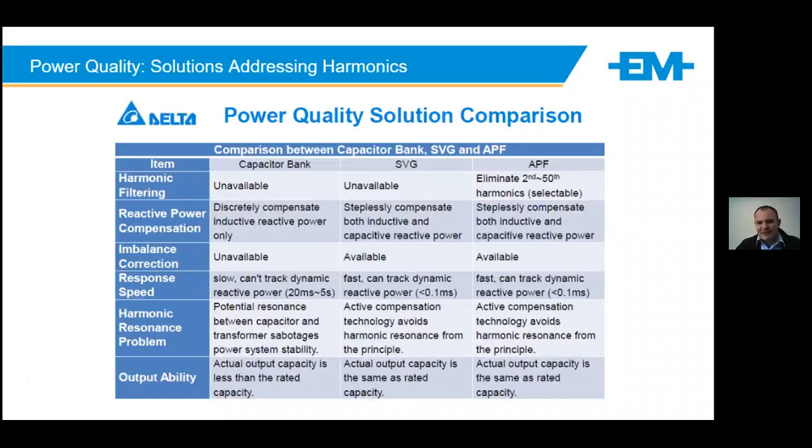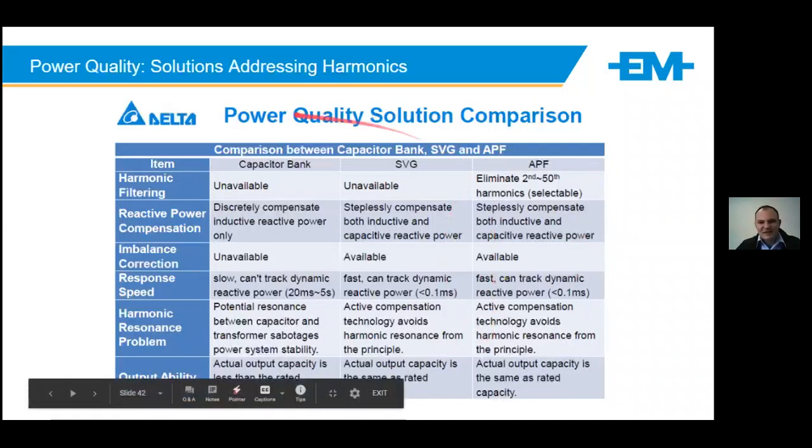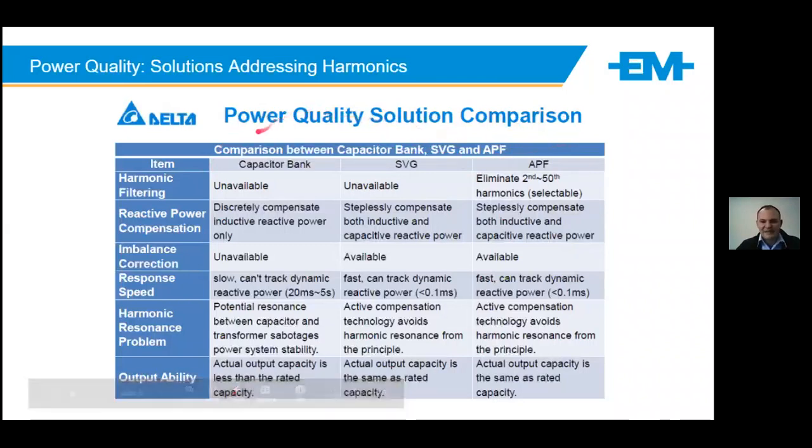An active power filter can do leading and lagging compensation and harmonic compensation. It does this by injecting the required currents in basically less than the half waveform, the 10 milliseconds, to smooth out that sine wave. In a lot of cases, it could be hybrids. The customer will need a capacitor bank to correct the cos phi, and you may need an active power filter to correct the rest of that harmonic current. Okay.